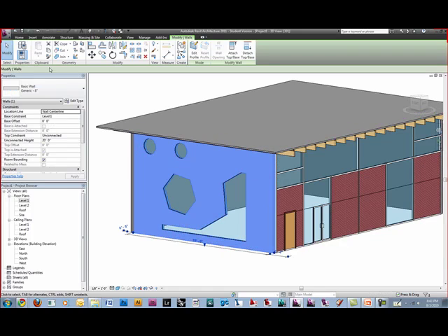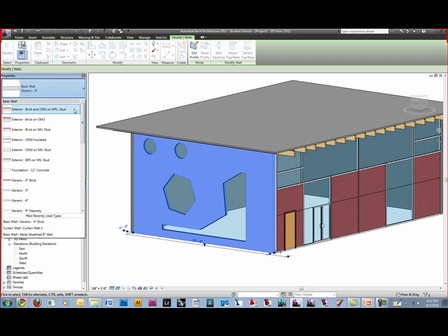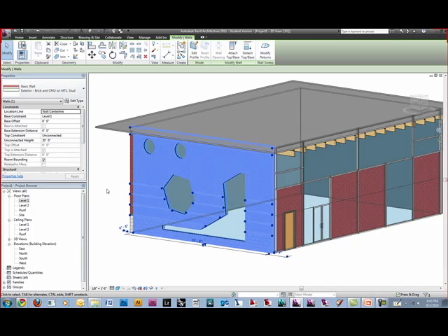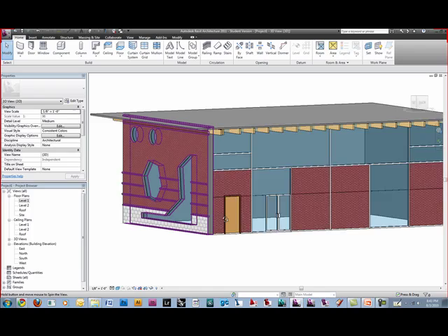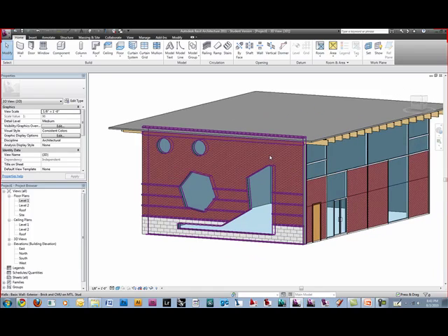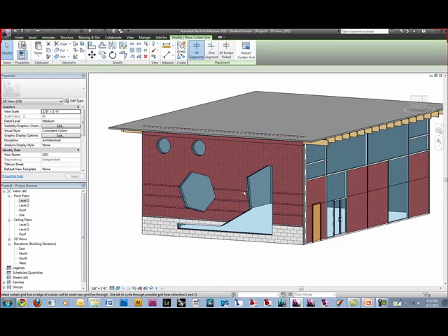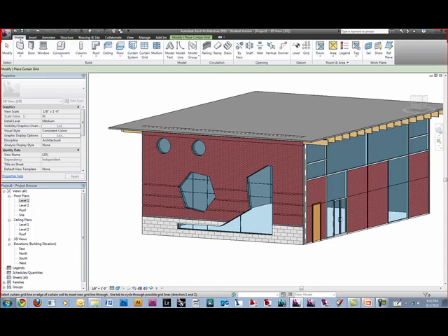And I should still be able to change this wall to say a different type. So I want it to be brick now, or some intense wall. It'll still automatically embed those in there with no kind of warnings or problems. So that's 2 different ways of doing it. And now that you have that glass wall there, you can go and you can say curtain grid. You can sort of cut this up. Let's go 1 segment, and I can say I want this one to have, whatever. I want another one here. And then I can put mullions on there.